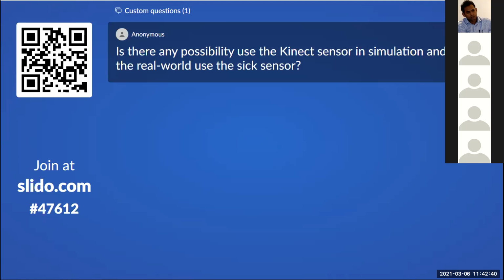So you have to study their data formats. I believe both have ROS packages. You can easily convert when you use ROS, because the algorithm or the processing part is independent of the sensors, as long as you obtain the sensor information correctly through the ROS topic.